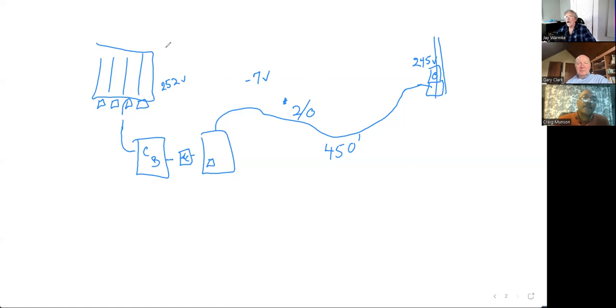Well, what if the operating range of my inverter is 230 to 250? I've exceeded that operating range, and now my inverter is going to shut down. Ain't gonna work. And that's the result of voltage rise, because the voltage has risen above the tolerance. And the way you deal with it is the same way you deal with voltage drop. You have to increase the size of the wire, decrease the distance, all of those kind of things.